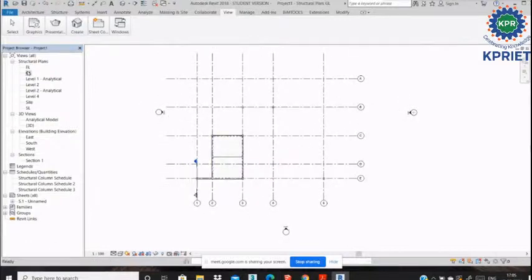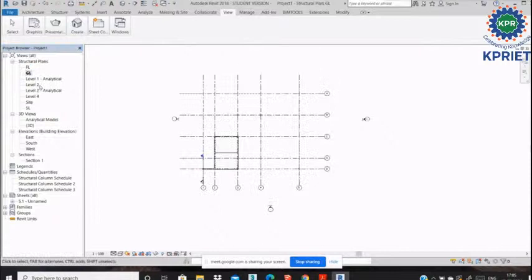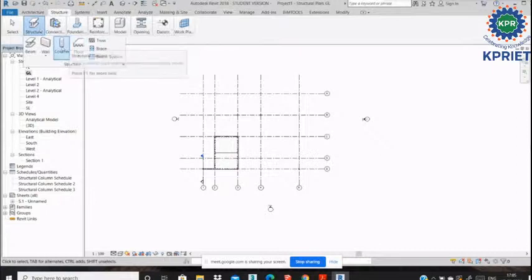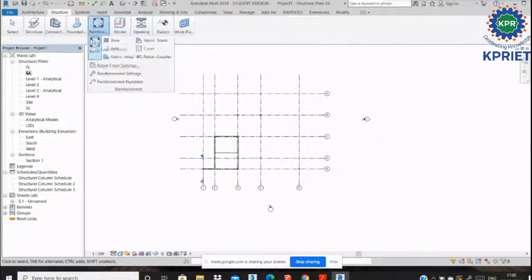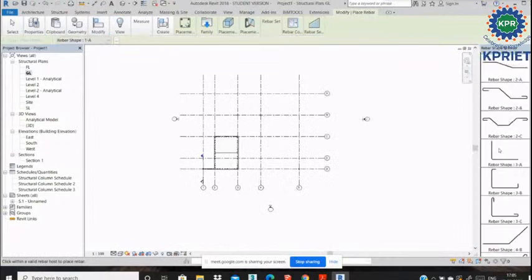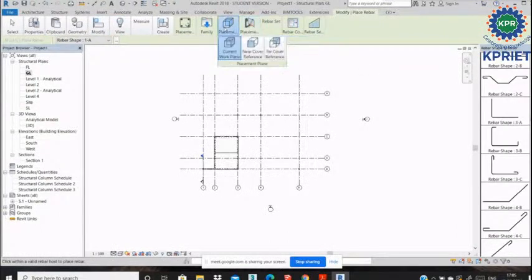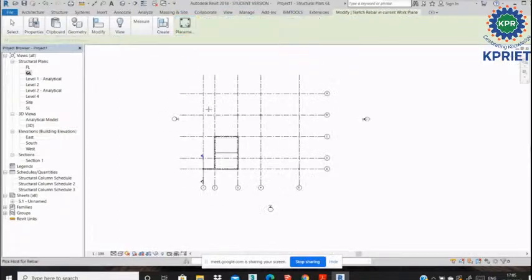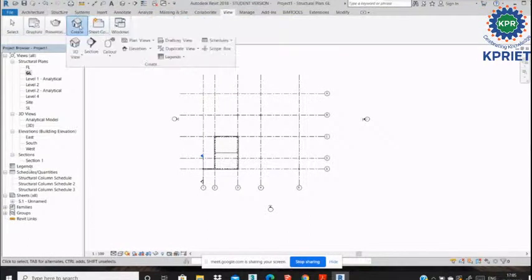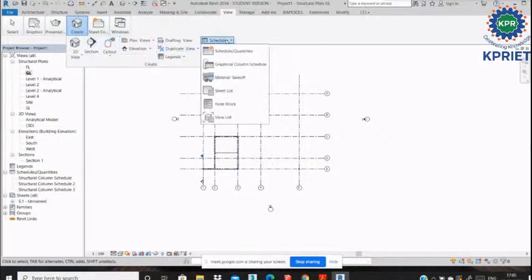Okay, fine. Now understand how to create the grid lines, how to create the column marking, footings, slabs, and the reinforcement. Simply go to Structure, go to Reinforcement, and directly give any reinforcement of any shape. You directly apply it with two methods only: place and parallel. Then go to any diagram you want to reinforce, click directly, and draw your reinforcement. Then go to sections. For sections, go to the View option, go to Create, choose Section, and cut your plan. Then for schedules, go directly to Schedule.